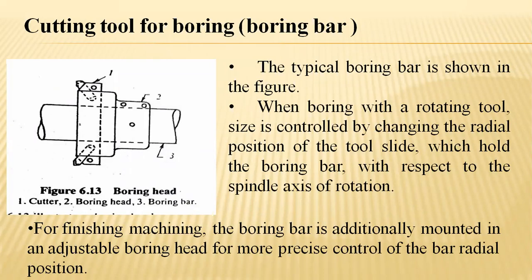particularly for finishing machining, these bore bars are additionally mounted on an adjustable boring head for better precise control of the bars in their radial, that is circumferential, positions.